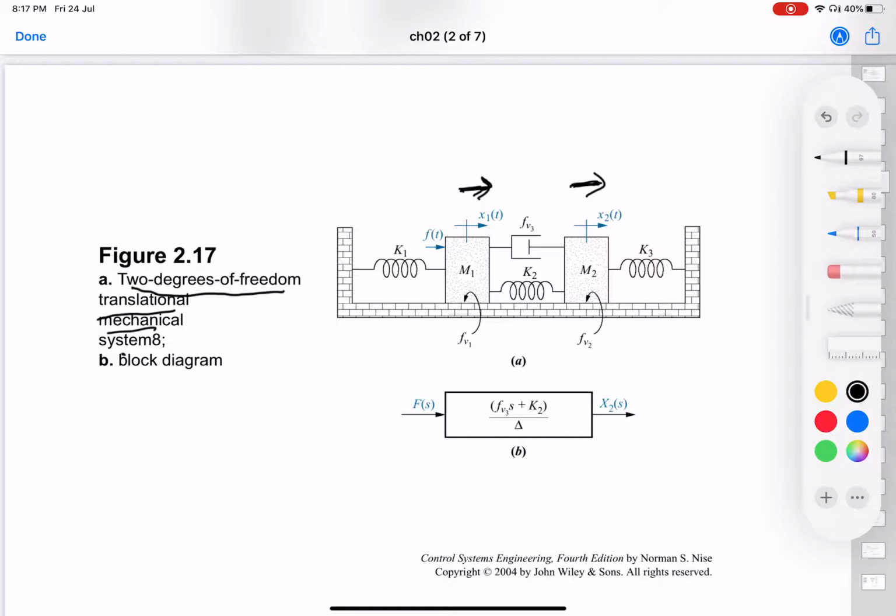And this also helps us in writing down the equations of motion more easily, because it's a linear system, we can assume one motion exists, right, and write down the forces and make the free body diagram for one mass, and then assume that the second motion exists and draw the free body diagram for the two masses. Basically, the motion x1(t) causes certain forces to be exerted on m1 and on m2. In a similar way, the motion x2 causes certain forces to be exerted on m1 and on m2, in addition to the external force that is acting, which is f(t).